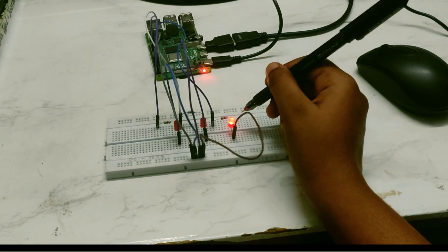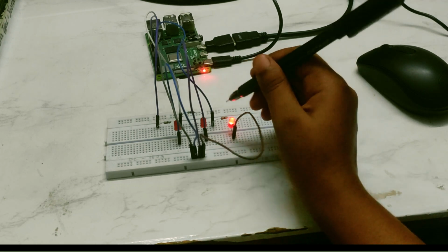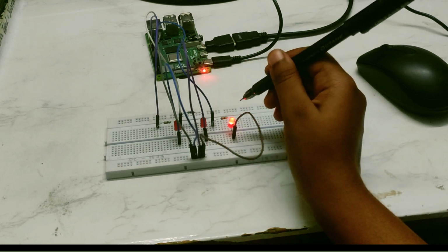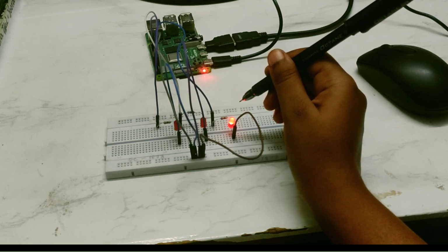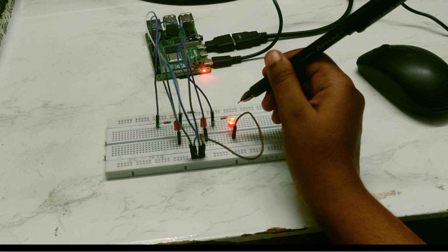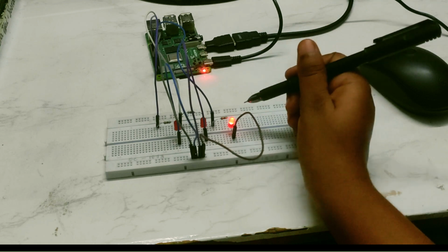Hence, these were the basic connections as per the circuit diagram. We can see that the LED of the LSB is continuously on. This is because internally it has a pull-up resistor, because of which it is continuously on. However, if we make use of any other GPIO pin, this would not be the case. And even when the program is not running, all the LEDs will be off. Hence, it's not recommended to use GPIO pin 2 unless it's for any operation related to I2C.